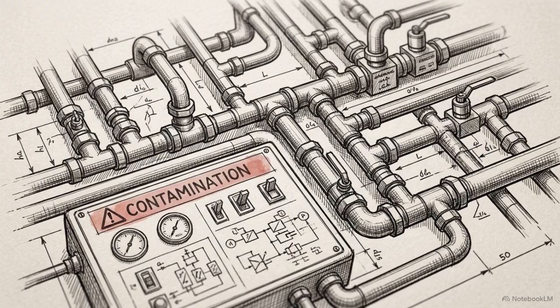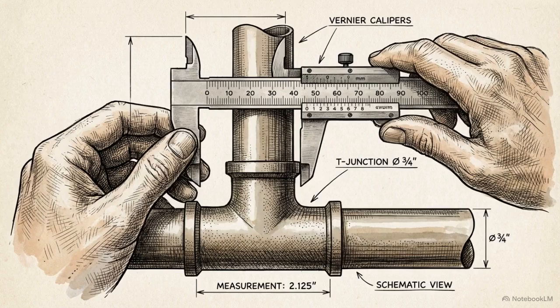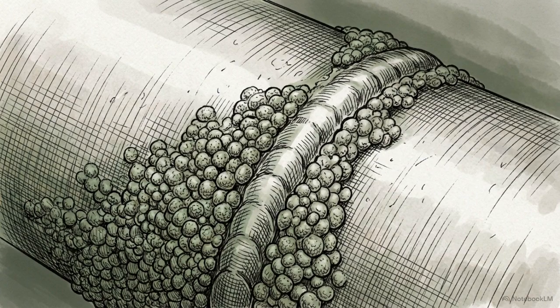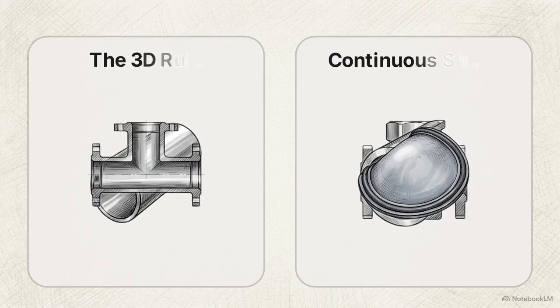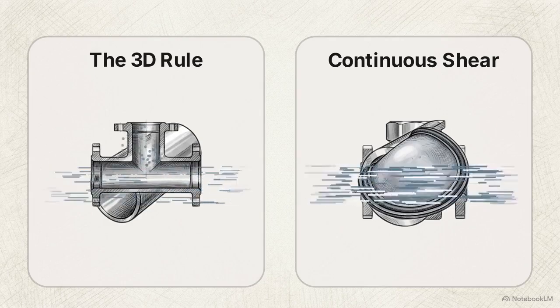As microbiological standards tightened, the industry adopted the stricter 3D rule to further minimize the volume of idle water. Yet, modern facilities strictly adhering to this 3D rule still experience severe, batch-ruining endotoxin spikes in their distribution loops. Traditional engineering operates on a baseline assumption that limiting the physical length of a dead leg is an adequate way to maintain water quality. The math and the biology of modern cGMP environments prove that mitigating dead leg length is insufficient. To guarantee purity, systems must achieve continuous fluid shear stress.